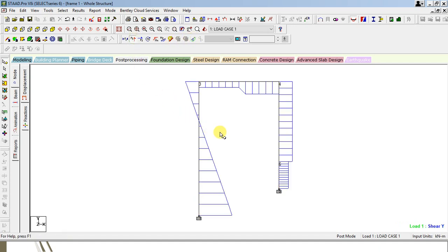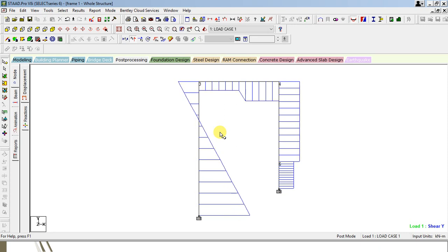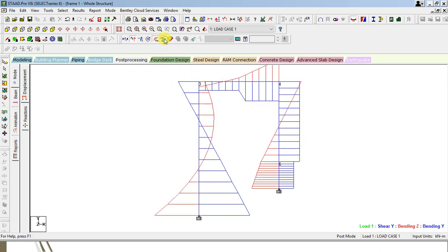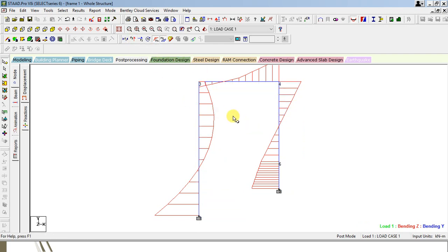shear force diagram. So here this is the shear force diagram. I am applying a concentrated force, therefore this kind of option appeared, but actually this will be the constant value. Okay, and now here again the concentrated or the nodal point load. Then next you check the bending moment diagram. Then here this is the shape of bending moment diagram. UDL, third degree, as a fixed support, so here there is a bending moment value. Again here point load, right?